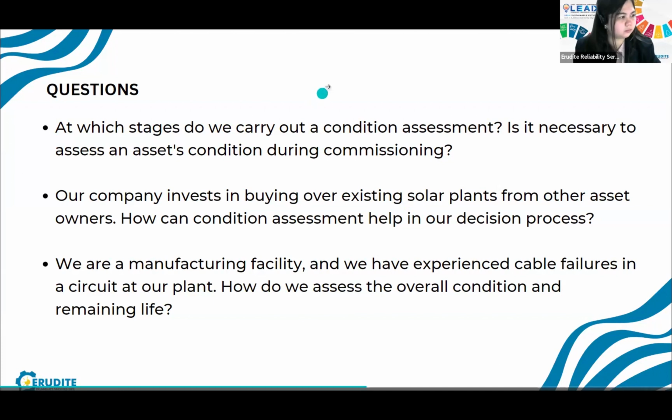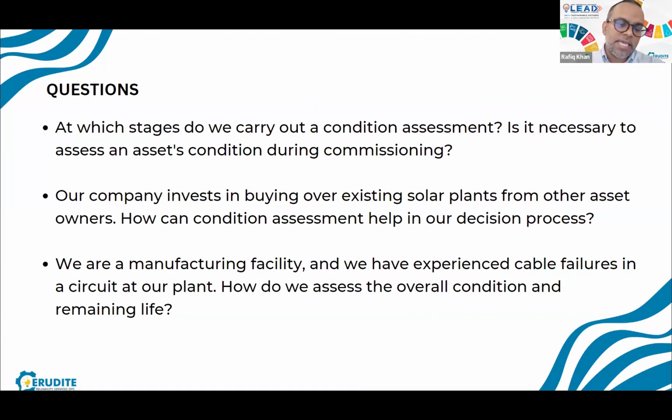We open up these cables, we do chemical tests, we do electrical tests, we do specification or dimensional checks to make sure that the cables are as specified and designed, and we are able to pinpoint a bit further the root cause of the failure. From this, we can also pinpoint if the other sides or other lengths of the cables have a likelihood of similar degradation. So it gives us an assurance that, if you have similar soil conditions, you would expect the entire length of cable to have the same problem.